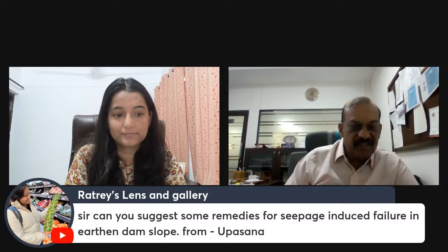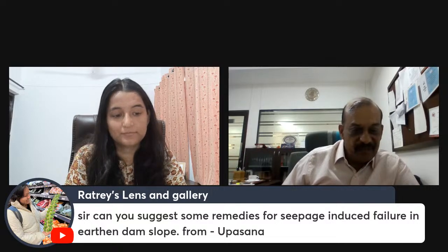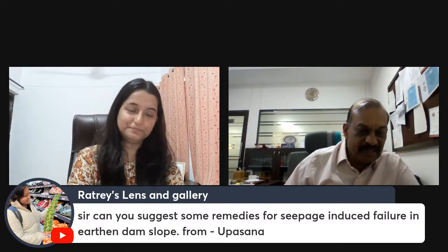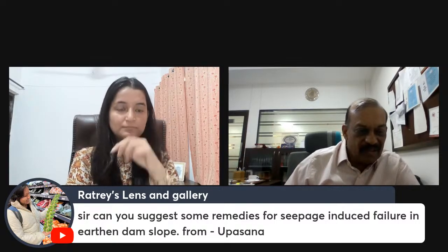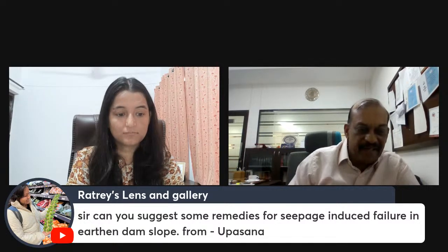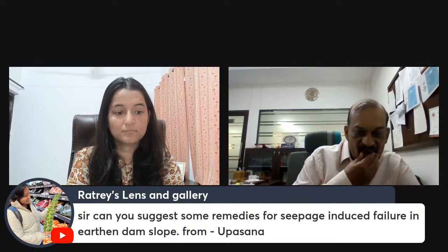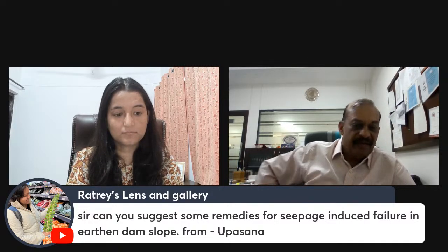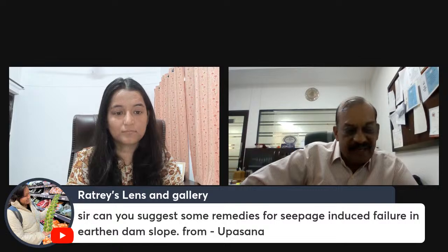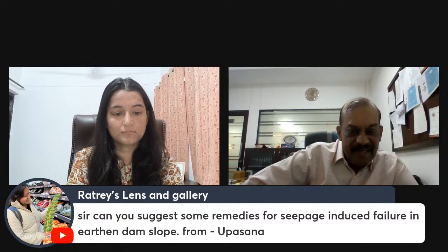Upasana, there are various solutions which have been implemented on various project sites, right from grouting to treatment at the toe to ensure that you can guide the seepage in a particular way. Even closely spaced piles. There are several solutions. Each case will have to be evaluated individually, and then you have to take a call.